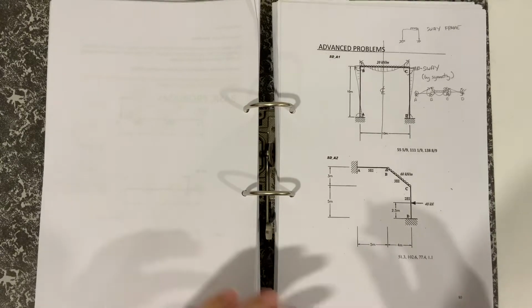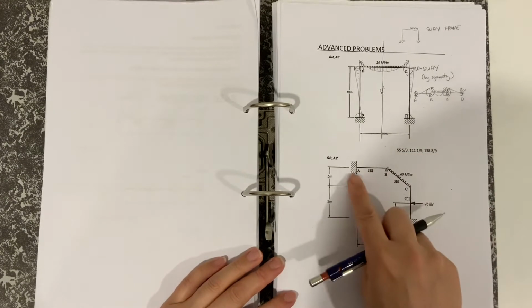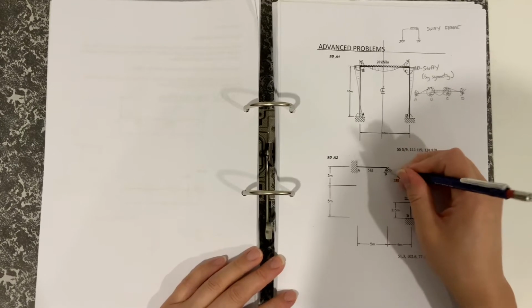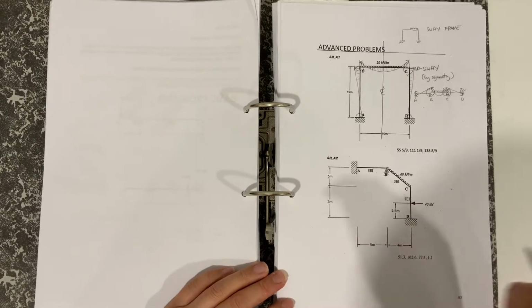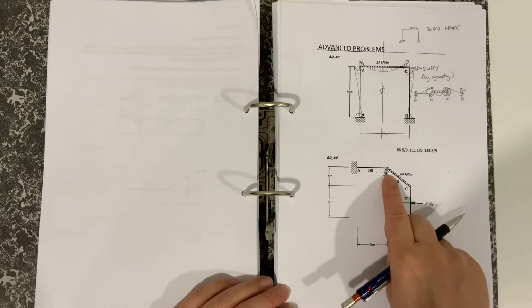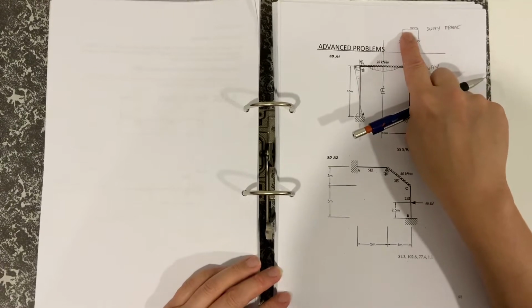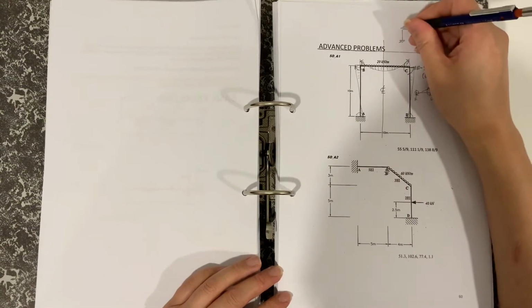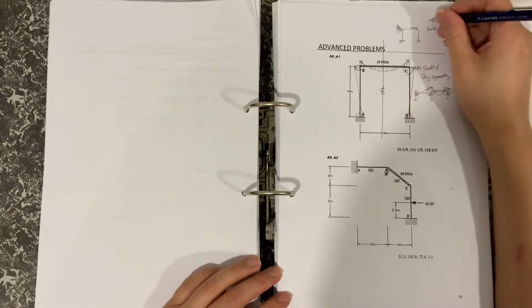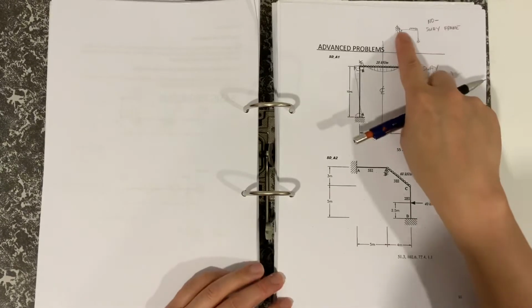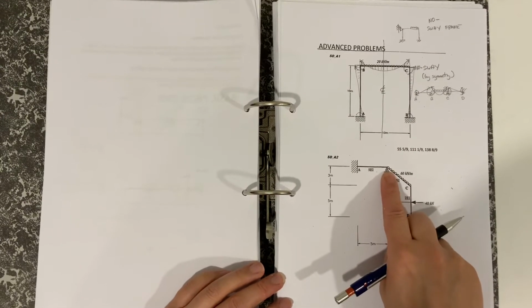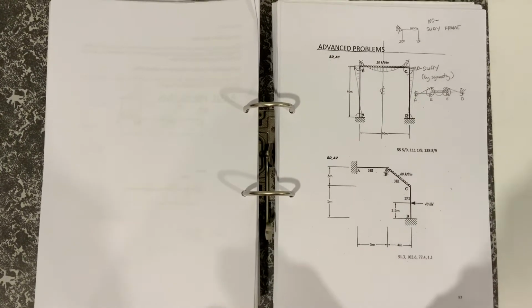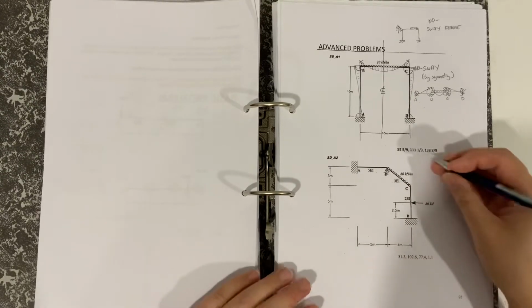And then the last problem, so there's this thing here, well, technically speaking that should be on the roller, but because of this, the frame has suddenly become non-sway. So going back to this one, this is a sway frame, but if you suddenly put a prop here, then the sway frame becomes a no sway frame. Right? So with a prop, that stops the sway, which is what this is meant to be doing here, stopping the sway. So you can do exactly the same trick.